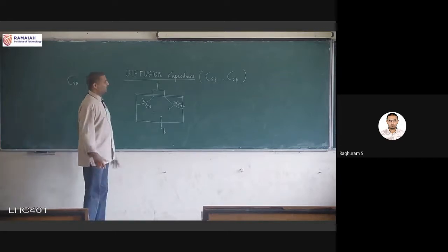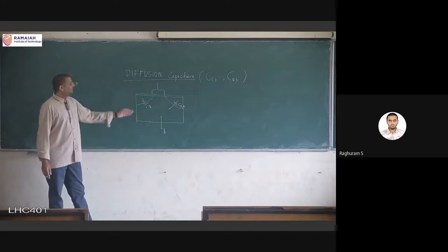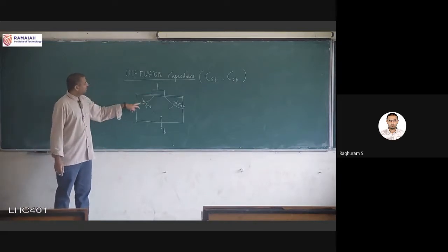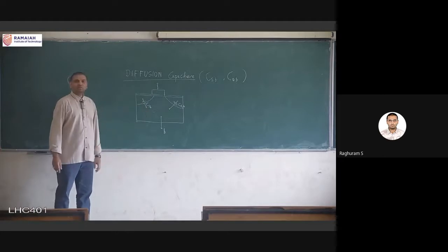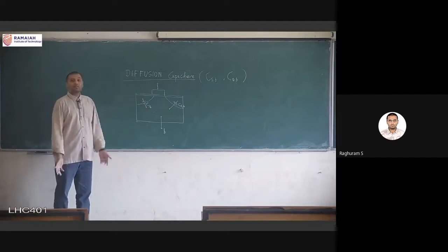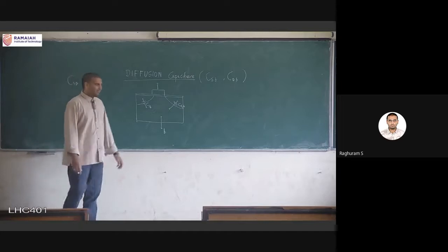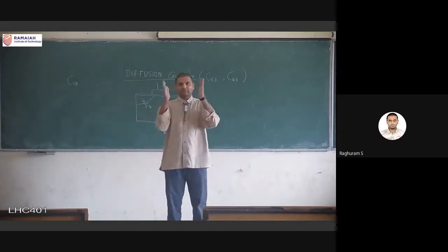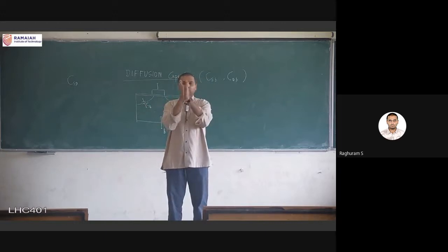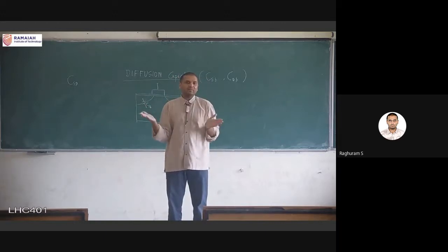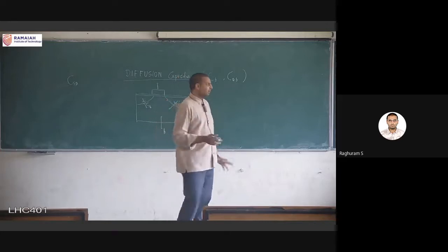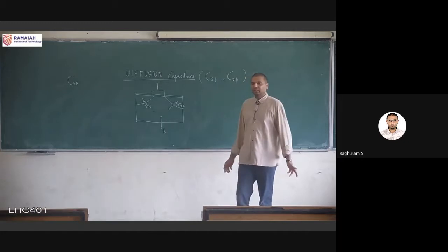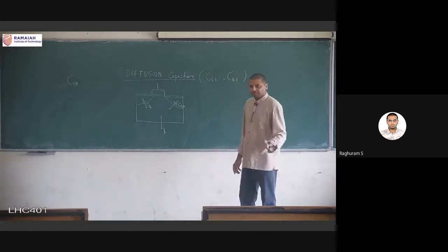Second thing to remember, okay, we simplified it. Where is the insulation? There is an N plus region directly touching the P-type substrate. Where is my insulation? For understanding why there is insulation, definitely, otherwise there is no capacitance, right? If I have two parallel plates that are touching each other, then both of them are at the same voltage. I cannot have any capacitance or any property. It is not a great advantage or anything. It's always a disadvantage to have capacitances because they slow down my circuit.